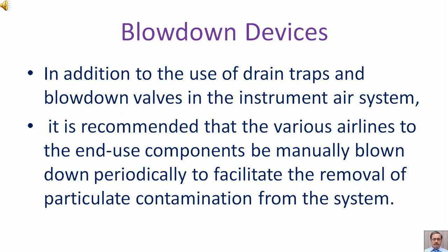In addition to the use of drain traps and blowdown valves in the instrument air system, it is recommended that the various air lines to the end-use components be manually blown down periodically to facilitate the removal of particulate contamination from the system.